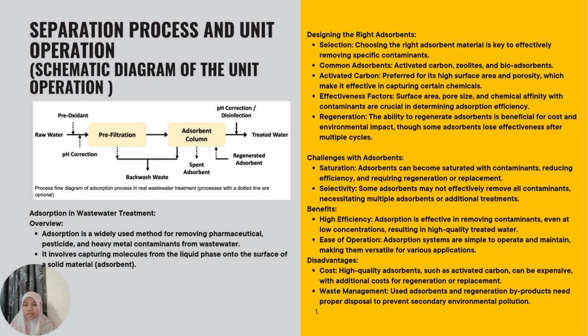For selectivity, some adsorbents may not effectively remove all contaminants, necessitating multiple adsorbents and additional treatments. For the benefits, it has high efficiency and ease of operation. For the disadvantages, high-quality adsorbents such as activated carbon can be expensive, with additional costs for regeneration or refinement. For waste management, used adsorbent and regeneration byproducts need proper disposal to prevent secondary environmental pollution.